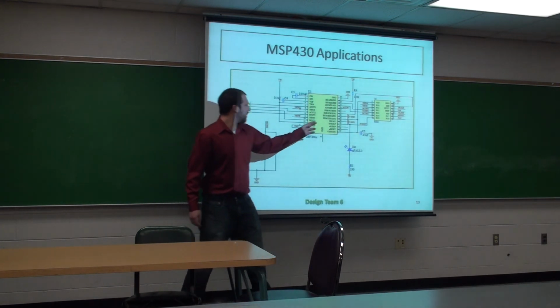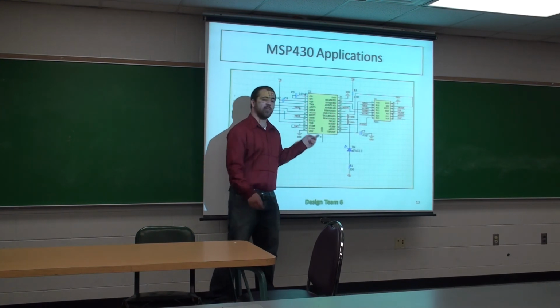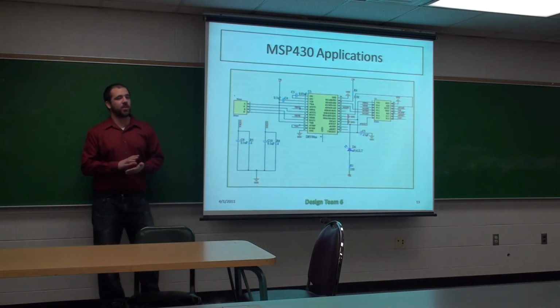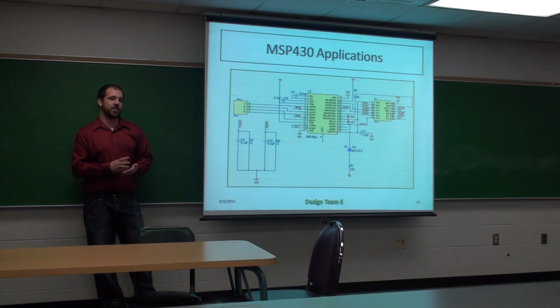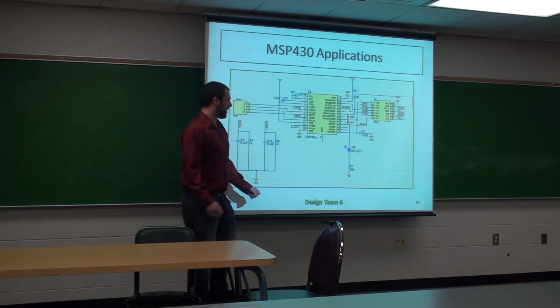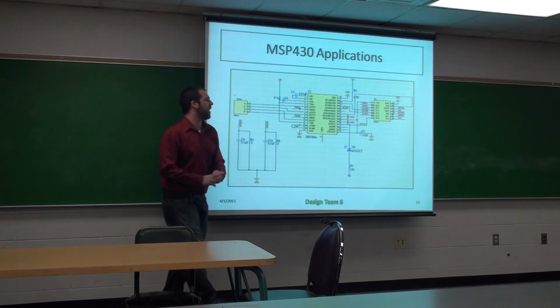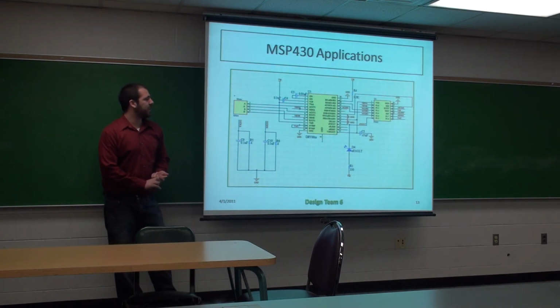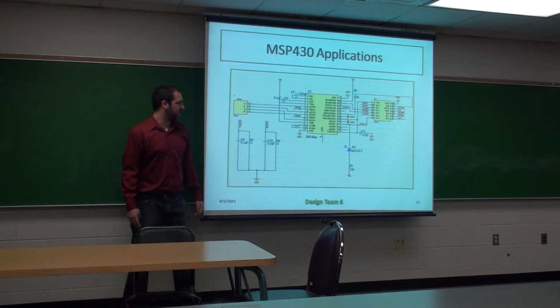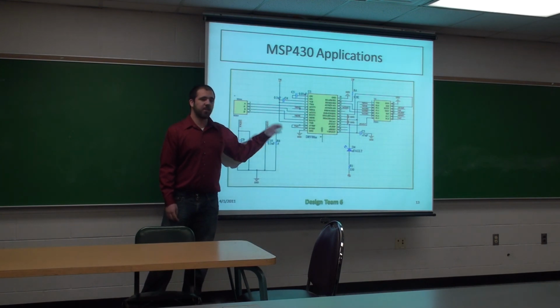We have a DAC. You can control the amount of current you want the motor to pull, if you want to have full current or use half current. Not a lot of people actually use it, but you do have control of it, so I'm just going to show it there. nRESET and nSLEEP. nRESET puts the motor back to its initial state, and nSLEEP is just a sleeping mode if you don't want to turn it off. Direction, you can go clockwise or counterclockwise. All you do is send it high or low.